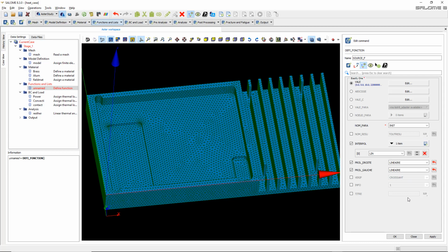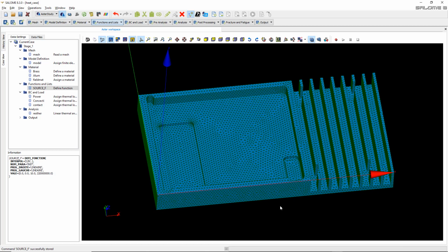So you'll see that I'm making kind of a mistake here, but I'll show you afterwards, and we'll go back to correct that after we have a look at the results. So make sure you follow through all the video to understand. Now, okay, I created this function. Now I have to create an actual transient load, because this load that I created here is a static thermal loading. So if you go into BCN loads, go down, so it's a bit difficult to find out where this is